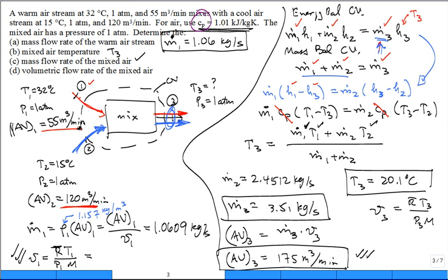But as engineers, we know what approximations work. And volumetric flow rate can often be treated as conserved. In this case, it's good to more than 3 significant digits. Okay? Does that make sense? Start changing pressure, don't assume volumetric flow rates conserved.